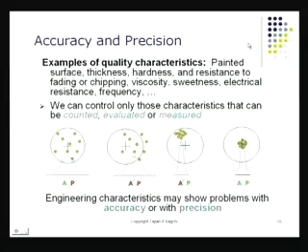This is something that we'd really like to have anytime we've got mass production. We'd like to have accuracy and also precision in the manufacturing of our parts. Let's see now what our task then becomes. We have a running process, and the raw process may have all kinds of variations. But what we should be concerned about is, is the process accurate? Is it producing, on the average, output that is staying right on target, number one.